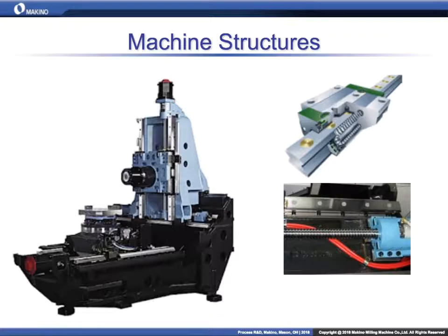And that comes from a whole realm of decisions, from the front of the spindle bearing down the shaft to the linear guides and ball screws that drive the Y-axis in this machine, to the column shape, the bed shape, the guides on the other axes, the table, all the bearings involved there. Each one of these is designed to be very, very stiff. We choose large sizes within the world of linear guides. There's a whole realm within the same style of guide. You can pick 25 millimeter, 35, 45, 55.